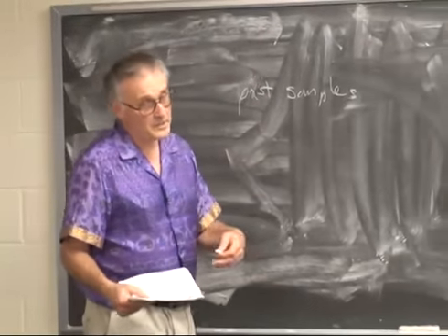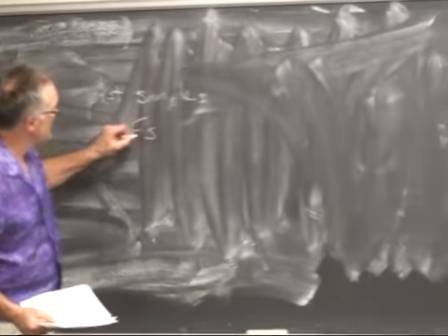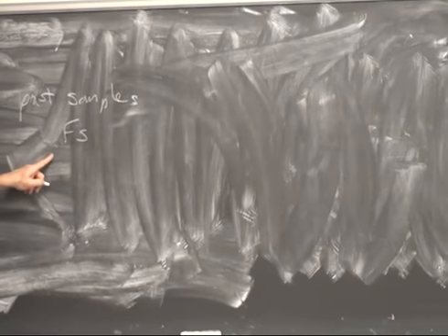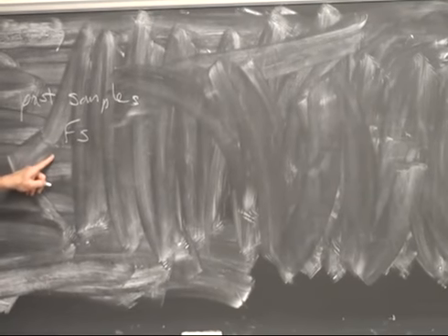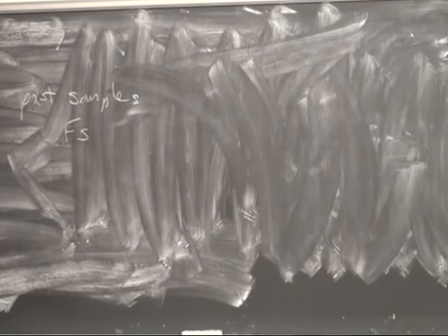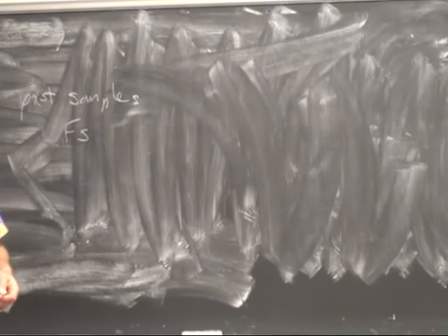So there's going to be some sample frequency, Fs, and we can look at as many samples in the past as we want to try and discriminate a signal from another signal. But every time you add more data, it increases the cost of the calculation. So there's going to be some trade-off in what we can discriminate versus how much time we can spend computing.